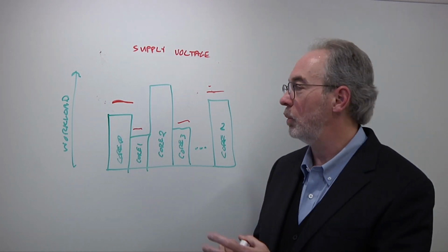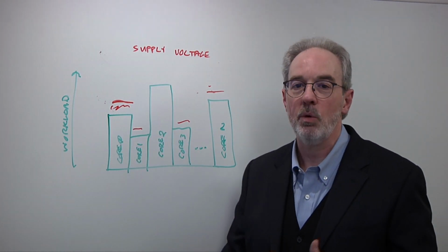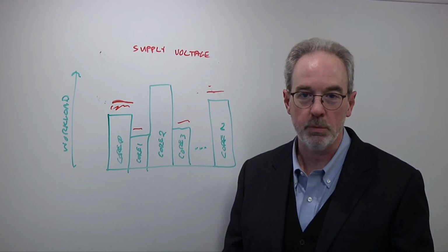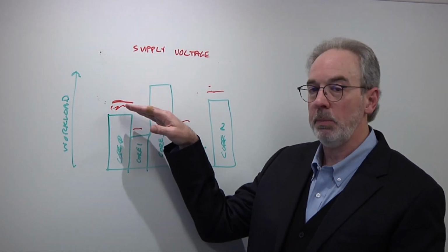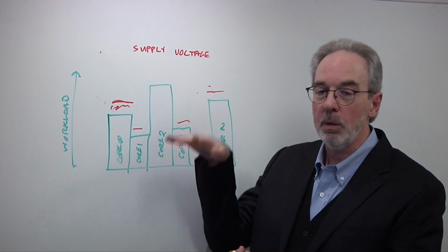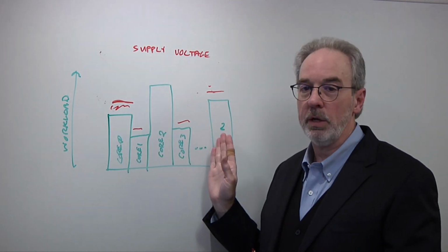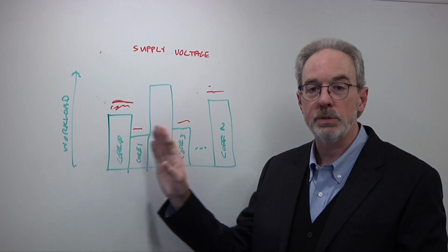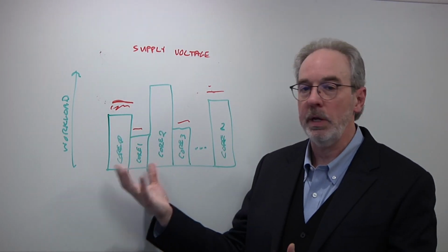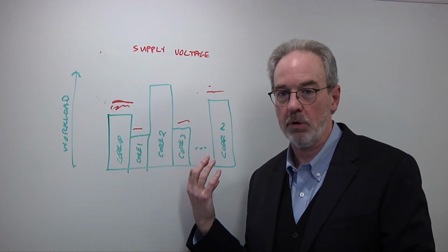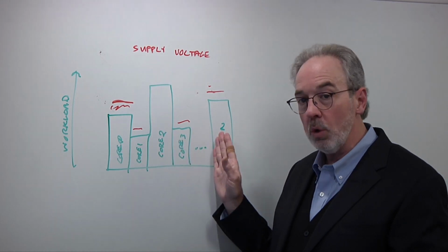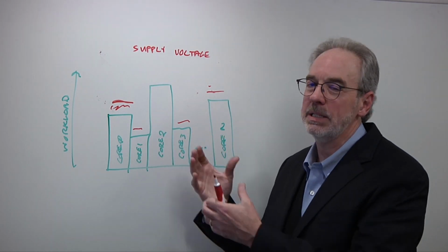I don't need it at day one, which means all of this is wasted power and energy and reduced reliability and more thermal stress. So having the ability to manipulate this and age gradually, bring that voltage up over time is key. The other, as you described, is these are not unique. They're not identical, right? There is variation, process variation, workload variation, aging variation across these devices. So being able to localize that aging control is a key factor.